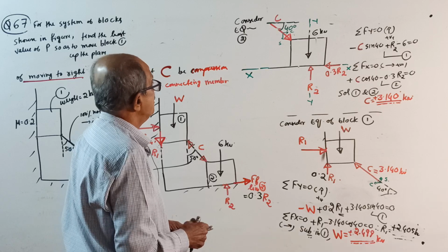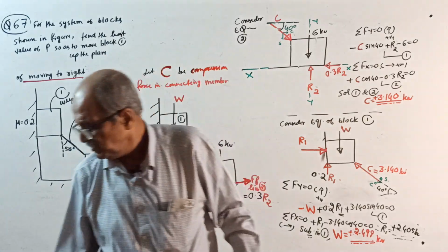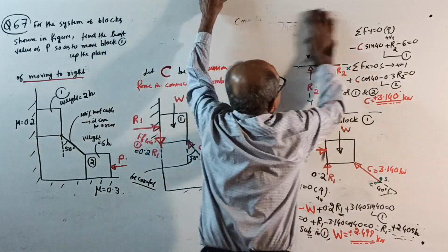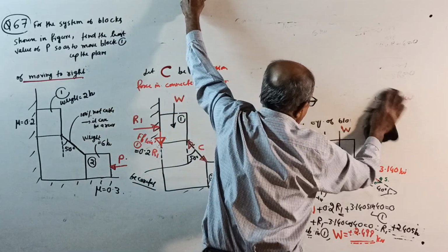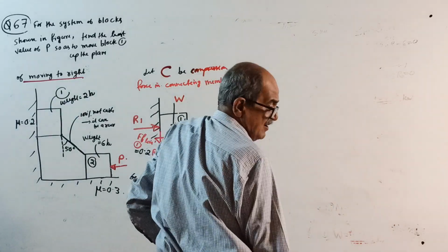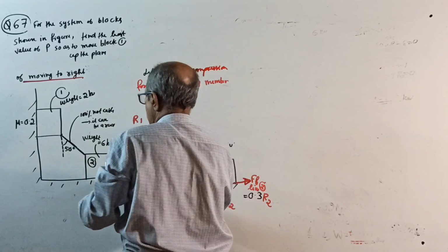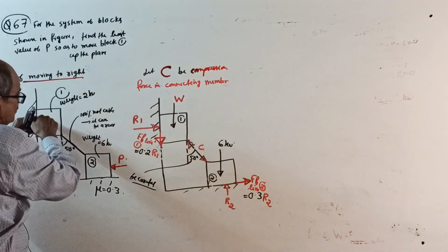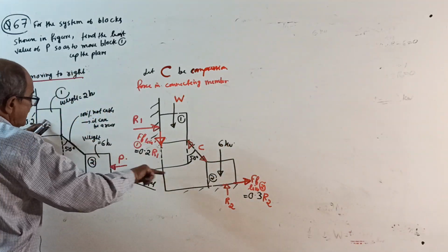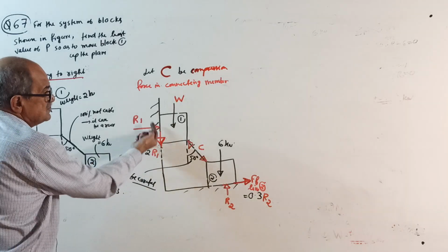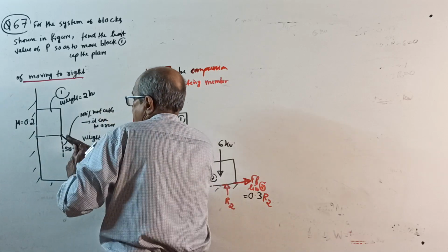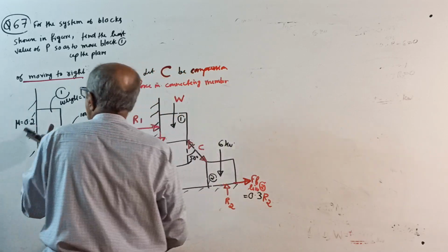Okay. Now, once again I have to solve. That sketch will not do. Okay, I will solve once again here. Now you have to consider it the other way. Be careful now. First, once again I will explain. Last time they had to find this weight when this block goes to the right side. So friction was left. When that was going right, this was coming down. Friction was up last time. But this time, this force P will push this block this side. As it pushes this side, this block will go up.